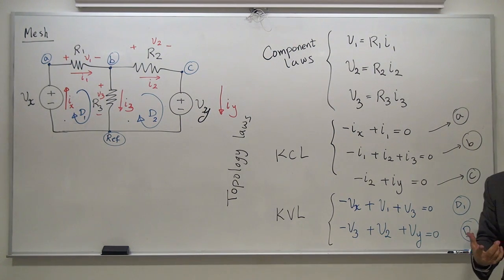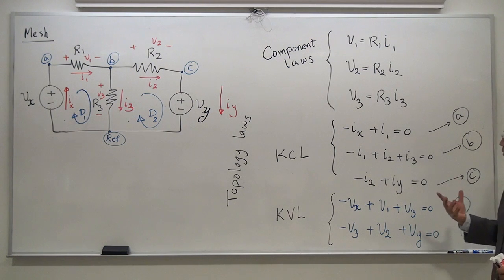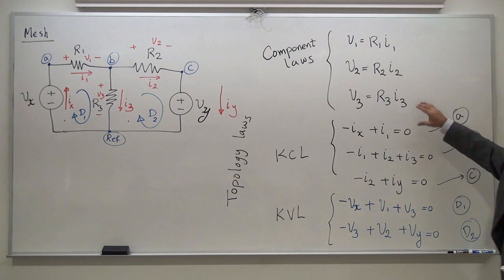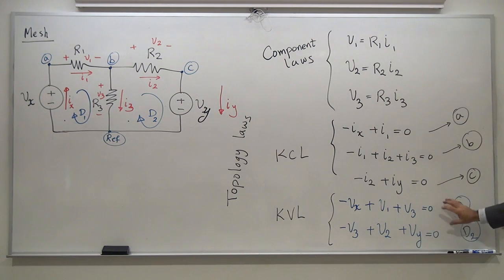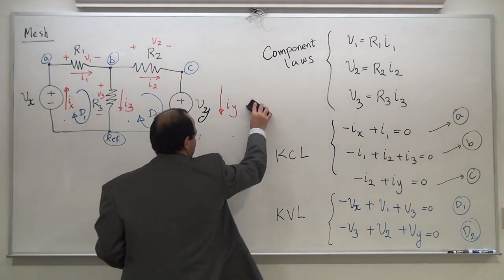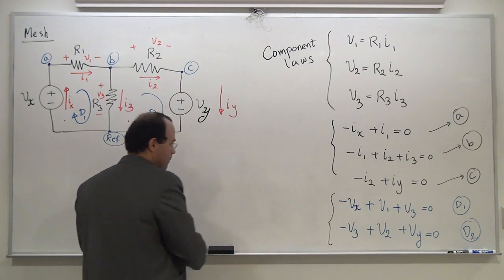A similar mentality can apply. Through a special transformation, we are going to take care of the KCL law now. I'm going to talk about that transformation in a moment. Then I'm going to put them inside this equation and collapse the system. Instead of 8 by 8, it's going to be 2 by 2, with KVL equations applied.